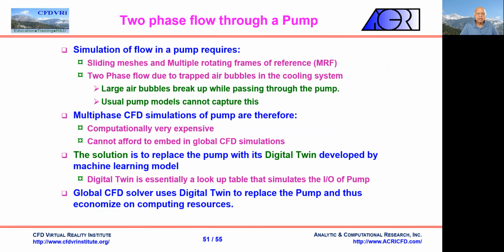What we do is first look at why simulation of the pump is expensive. It's expensive because pumps require sliding meshes and multiple rotating frames of reference. Okay, the pump is moving, blades are moving, flow is moving through it, there is a stationary part. Then there's a two-phase flow due to trapped air bubbles in the cooling system.